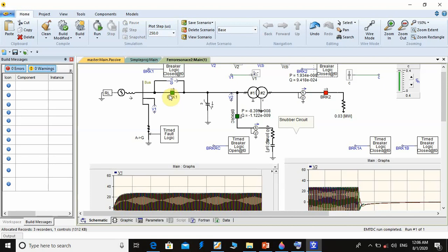because for the circuit breaker there is a danger of restrike. When the TRV is very high, that means the recovery voltage is more than the insulation. Maybe there is a risk of restrike across the circuit breaker contact. Okay, with load there is no problem, or no risk for de-energizing a transformer with a long cable when the transformer is loaded, or just loaded by 10% of its rating.